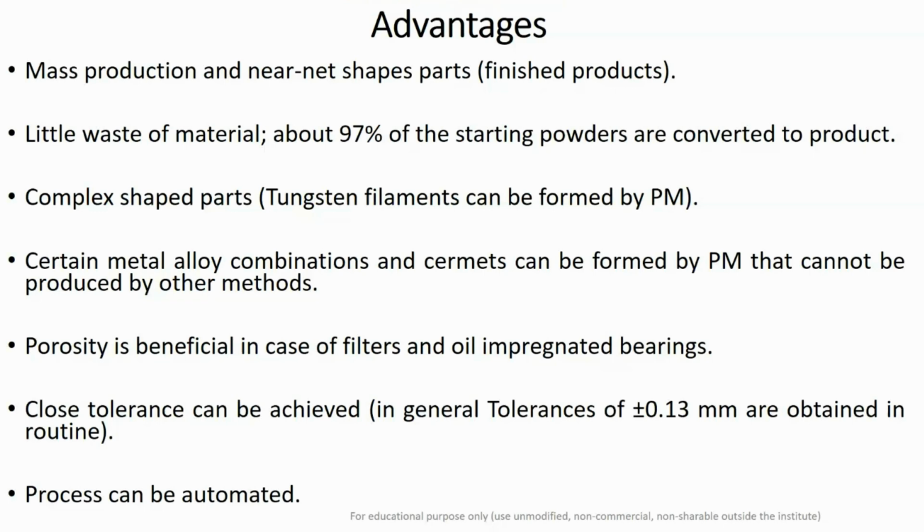While pouring into the powder feeder, there are chances that you lose 1 or 2% of the powder if your process is not automated. And from the powder feeder to the die cavity, sometimes some powder particles stick inside the feeder. In the next lot, or if you want to change the part or the material, you have to take out that used powder which has stuck inside the powder feeder. So only 3 to 5% powder wastage is observed.